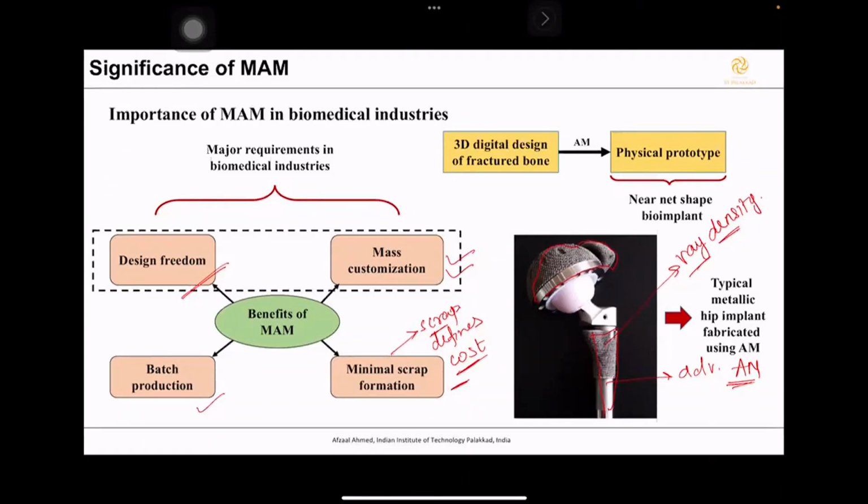As Afzaal rightly said, slurry-based processes, for example abrasive flow finishing or magnetorheological finishing, can be used. The problem is you can't control them, and there is a chance the abrasive may embed inside and create a problem. Dr. Subbu, you cannot control the process parameters. The other important thing is you cannot control the dimensions of the component. You have to compromise the dimension. That is also true.